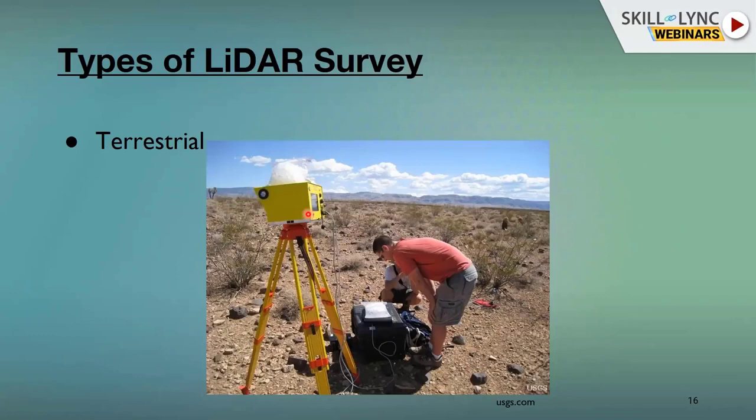When we go for small scale maps, people go for airborne LiDAR survey. When people go for large scale, they use terrestrial LiDAR and mobile LiDAR survey. This purely depends on the scope of work, what kind of work they are going to do, and what exactly output they are going to get. Based on that, they take a call and plan accordingly.